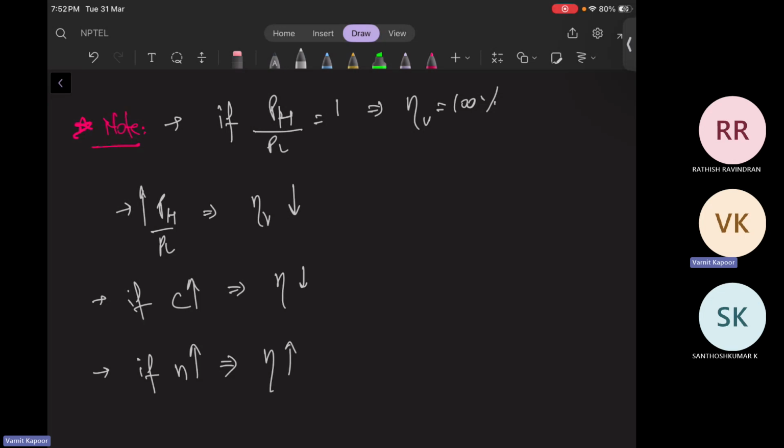So from an IC engine perspective, using a monoatomic gas increases the knocking tendency, as we have seen there. But here, in terms of the compressor, it increases the volumetric efficiency. There is a need for clearance volume because the piston should not hit the walls of the cylinder, and there should be some space for thermal expansion as well, as we have seen in IC engines. So there is similarity here and there.